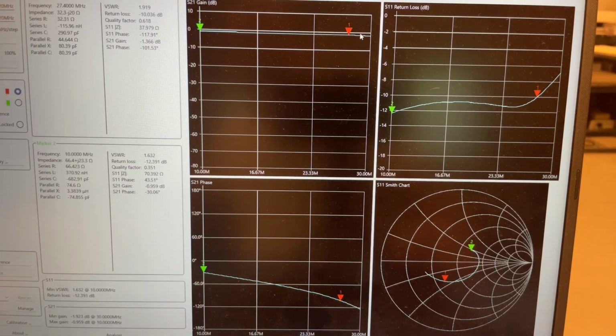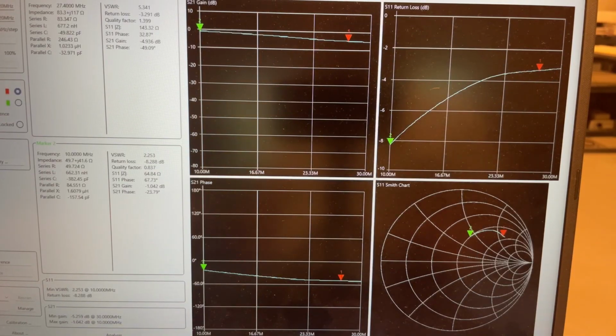And we're getting a little bit of a roll off here at the very end on the high end. Okay, so that's the calculated value, but remember what we said, that there are some parasitics. Even in your test setup, there might be some parasitics, but certainly on the board. So now I'm going to go to the next standard value down, which is 680.